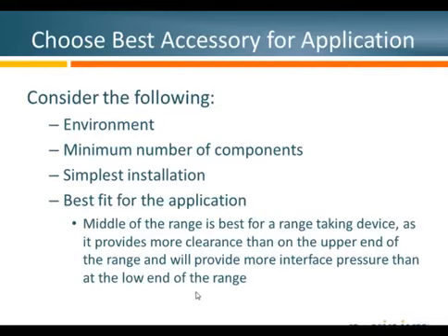And the easier it is to install and the simpler it is, the less chance there is for error, and therefore the increased reliability. And as far as application itself, a lot of your accessories nowadays are range taking, and you really want to try to choose one that, if you have a particular cable, fits in the middle of an application range. That's better. Closer to the middle versus at the very low end or the very upper end.